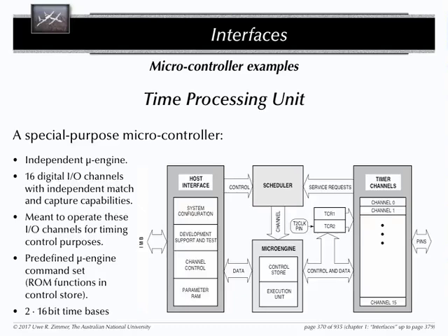If you have anything else, you always have to consider what is the impact of this communication protocol I have with the other controller. So you outsource something to an external controller, but eventually you have to do some message passing, exchanging some information. Now, any form of exchanging information means that you need to synchronize, usually, with the other partner, and that can influence the real-time behavior on the other side.